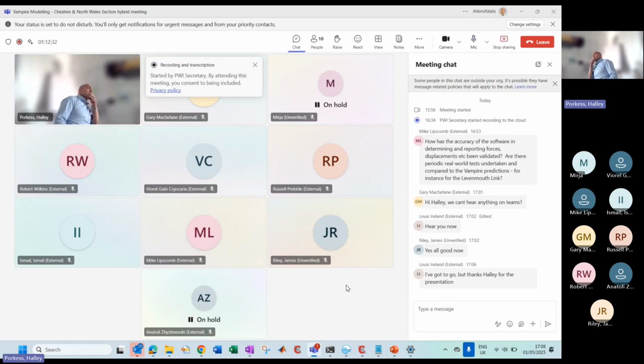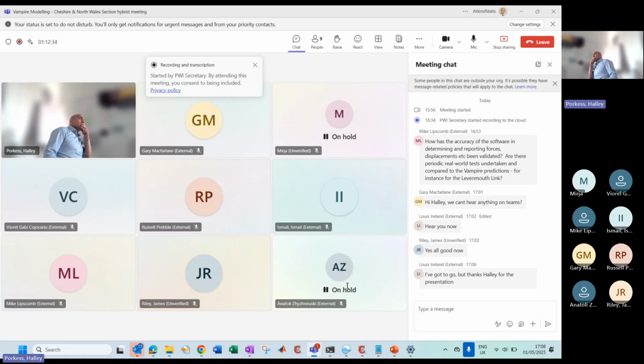I have one here. On the Crewe project, our limiting radius for check rail was 250, wasn't it? Not 200. Yes, but that was a pre-reference. No, it's not in the standard. It was particularly relevant to Crewe because of dangerous goods, the nuclear flasks, and that's what they were worried about. Do you reckon if we'd done the Vampire modelling, we might have proved that we could possibly have adjusted or not used check rails? We had a track that was kind of weaving like that.